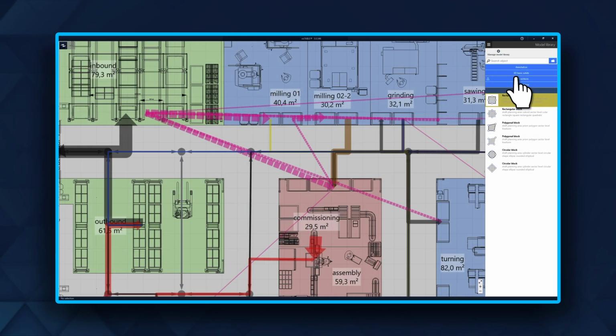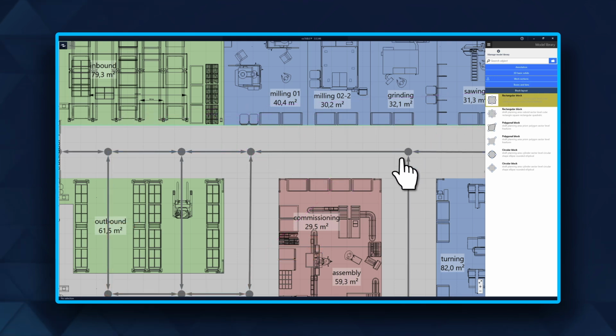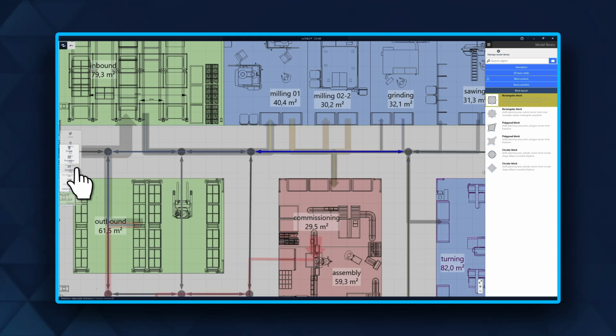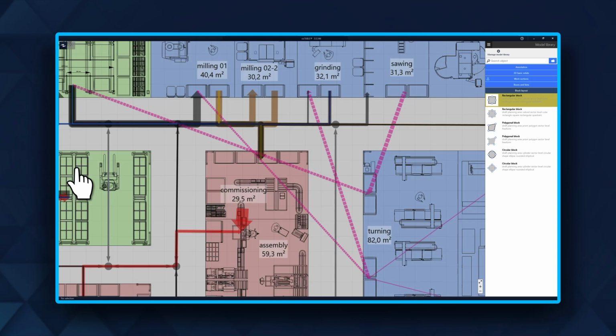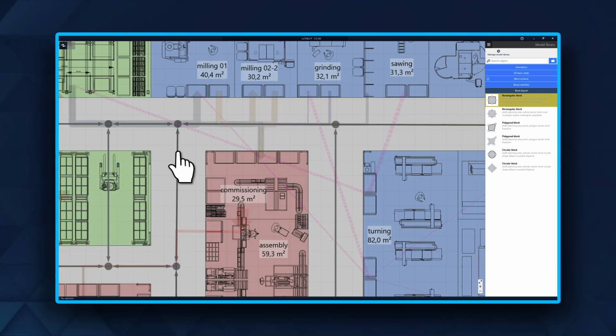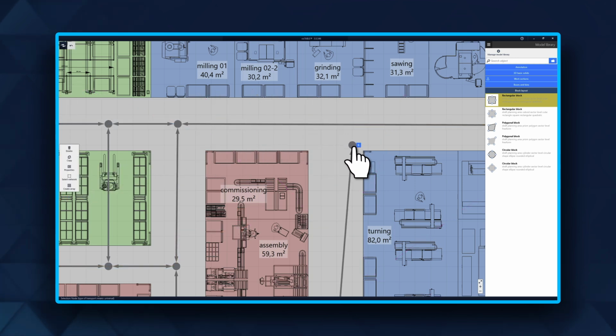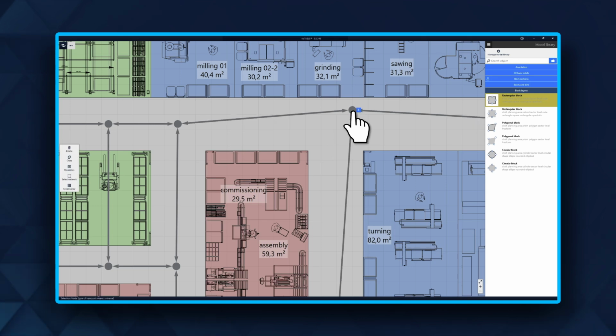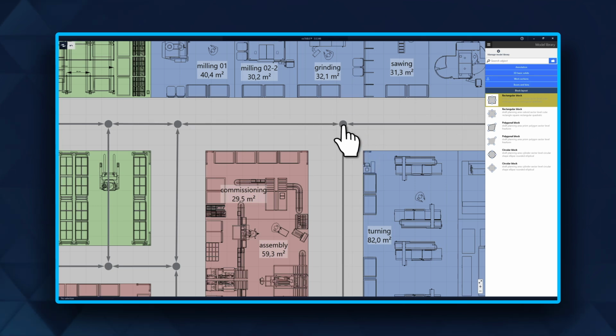Something that can also cause routing failure are one-way transport paths. To fix these, you can change the direction or make it a two-way path. Another source of errors are dummy connections if network nodes are not connected correctly. To check this, drag a node. If the paths don't follow, you've got a broken link. To fix this, just drag the node onto the network path to connect it. If everything is correct, the paths will now move if you reposition the node.